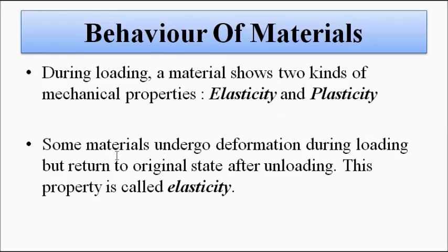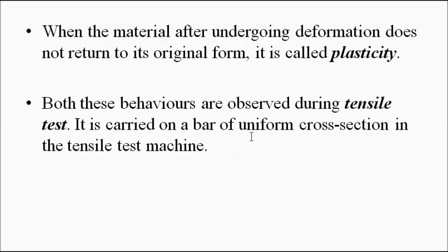Okay, so during the process of loading, the material undergoes change in shape and size, and when the stress is removed, returns back to its original state, then the material shows the property of elasticity. When it does not return back to its original form, then it is called as plasticity. So both these behaviors are analyzed and observed during the tensile test. Okay, it is very important. It is used for the analysis of tensile strength, the modulus of elasticity, ductility, hardness, toughness. So all of these properties are analyzed during the tensile